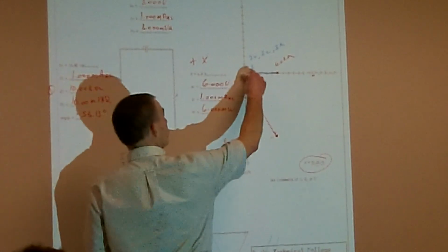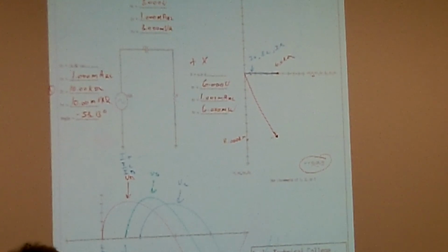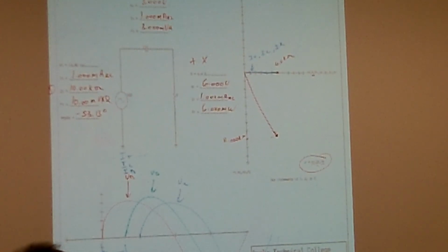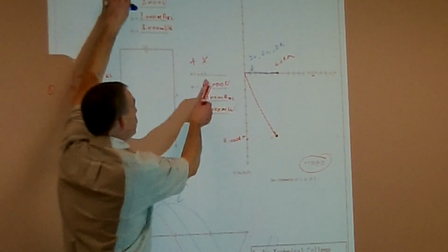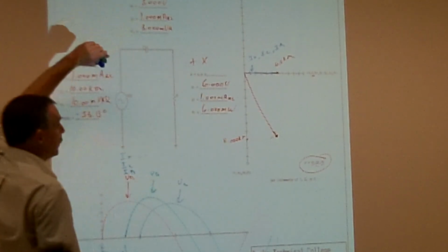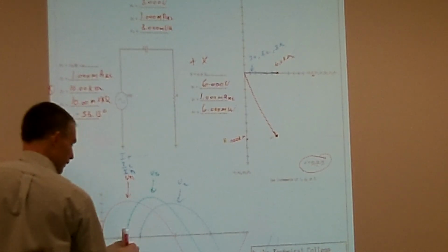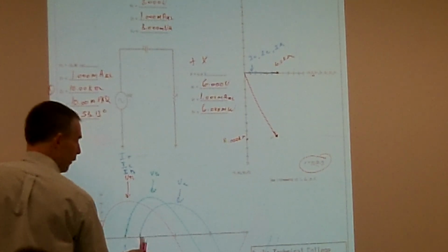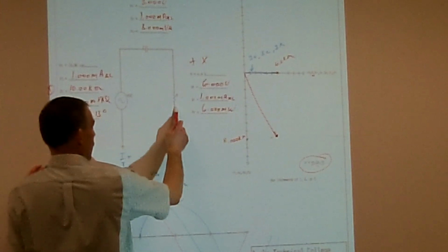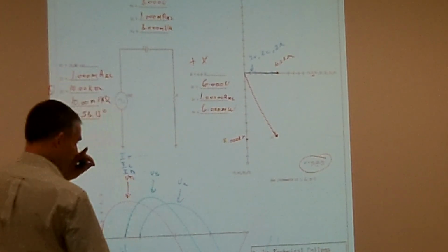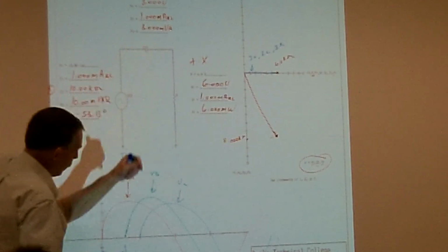So when we're looking at this, am I more capacitive or more resistive? More capacitive. Okay? And it holds true because my capacitive reactance is 8 kiloohms and my resistor is 6 kiloohms. So I'm more capacitive. And when it's more capacitive, my voltage source is going to be following VC more. If I were to drop this resistor out and short it out, VS would follow VC. If I drop my capacitor out and short that out, then my VS would follow VR.